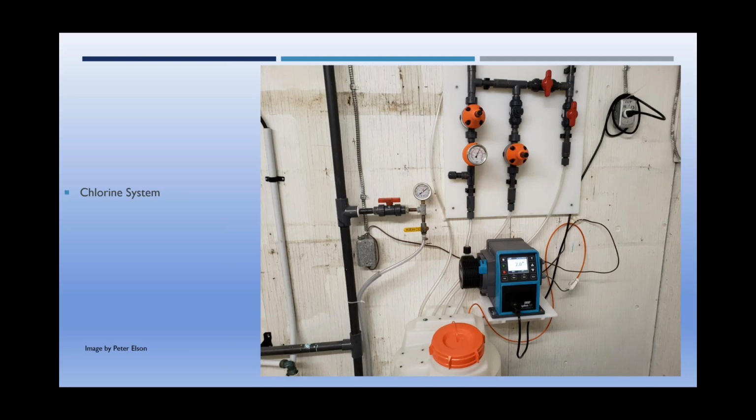And it ended up they had a serious bacterial problem in that system, and that whole community had to be evacuated for a couple of weeks while we went in the middle of February to flush the lines, clean everything out, rechlorinate the reservoir, chlorinate the well, and try and get that system back up. That cost well over $100,000. That was completely unnecessary. All he had to do was go in, look at the tank, or write down the number every day. That's a huge expense. It was completely unnecessary because he just failed to do the most basic monitoring of the data, which he had. It was there.